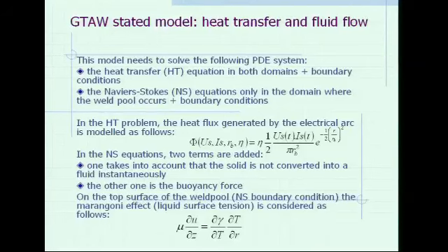And the two parameters we'll discuss later are this Gaussian radius, so the distribution of the Gaussian, and this coefficient eta, the efficiency of the process. These ones are not well known from the process. It is known, I would say, experimentally, that you fit this data to this value. Basically in TIG, Gas Tungsten Arc Welding, we say it is 0.7, and here you will take something between a radius of 2 to 3 millimeters. It fits quite well, so it's fine.